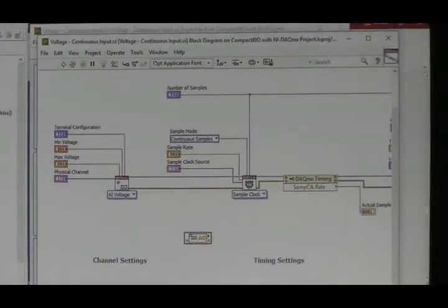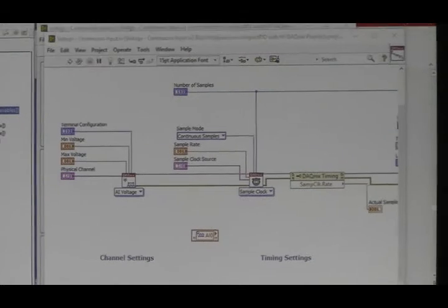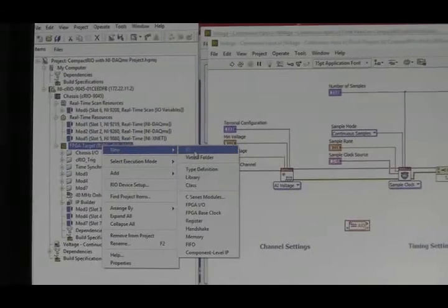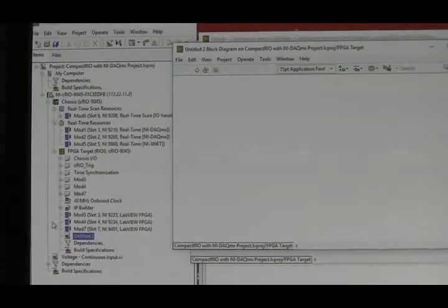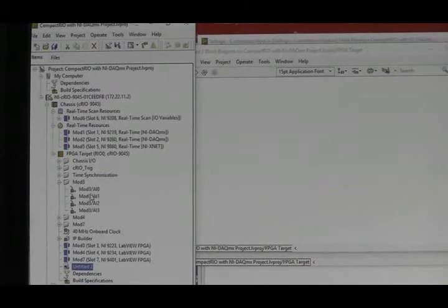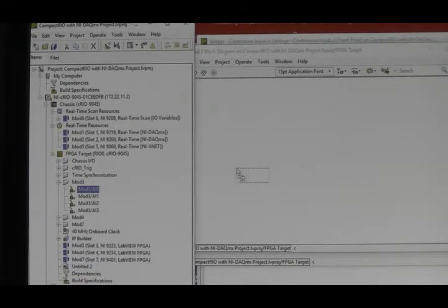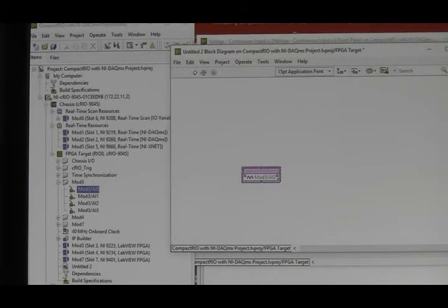And then down below, I can create an FPGA VI, go to the block diagram, take one of my I/O nodes, and drop them into LabVIEW FPGA just like I would on any existing CompactRIO controller project today. So you can see, other than the configuration options up here and having these new buckets in the LabVIEW project, the experience really isn't that different. I can continue to program just like I do today.